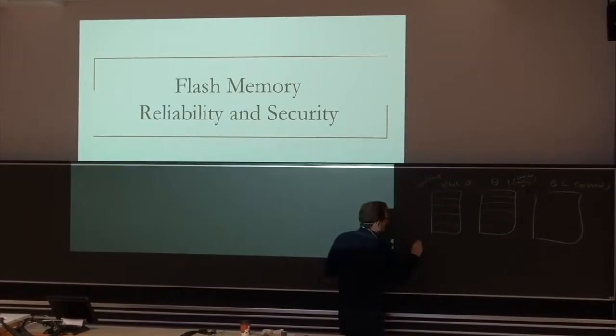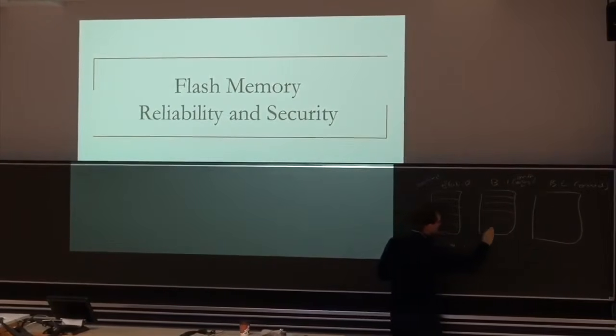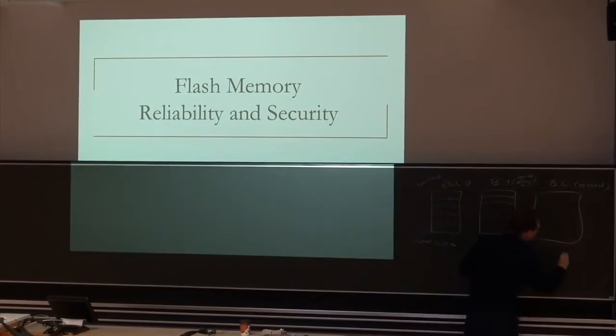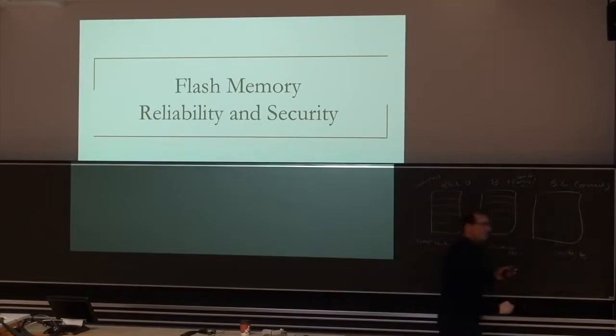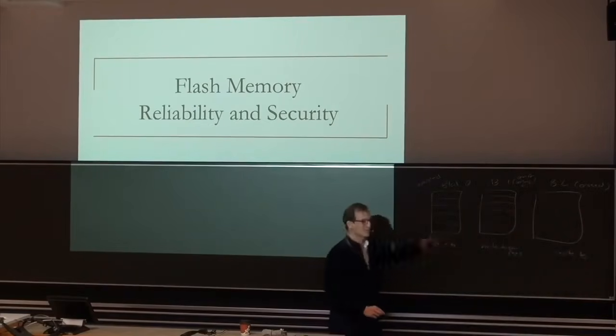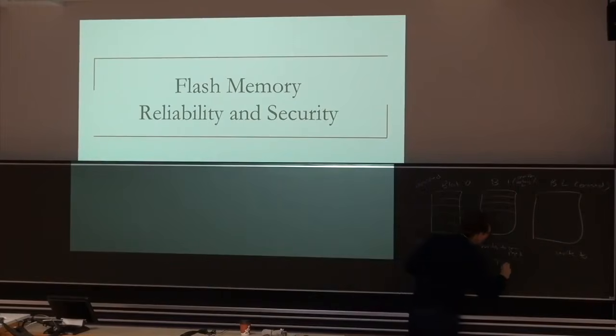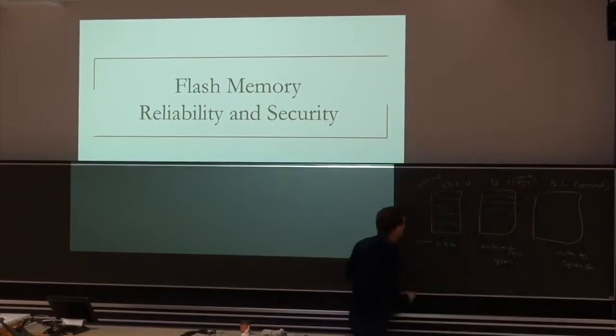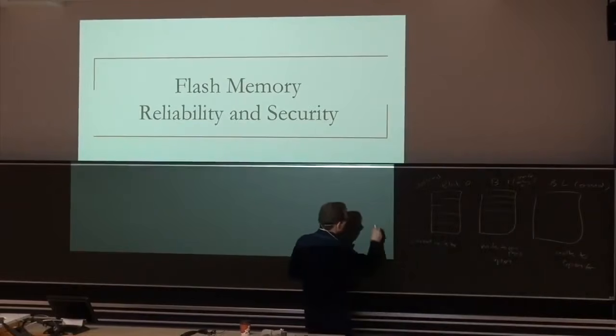This block you cannot write to, because writing requires erasing. This block you can write to some pages. And this block, yes, you can write to, but you're waiting such that you can utilize this part first, because this is open for writing also. So this is open for writing. This will be open for writing in the future after you're done populating this. So basically, flash controllers need to maintain a logical block address to a physical block address mapping table.